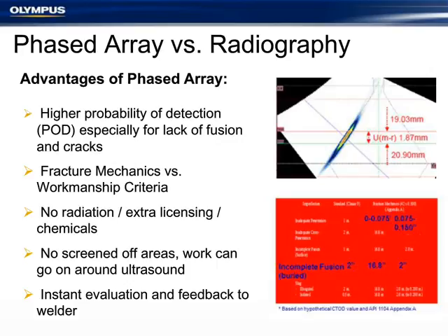From a physics standpoint, ultrasound in general and phased array, advanced phased array and TOFD, if you look at most of the probability of detection studies out there, generally will score higher in most trials done between the two for welded pipeline. From a physics standpoint, ultrasound does detect linear defects like lack of fusion and cracks better than a radiographic technique, where radiography has a slight advantage for rounded defects like porosity, slag, this kind of thing.